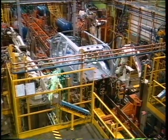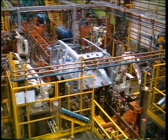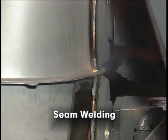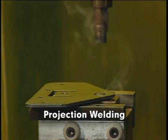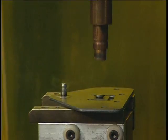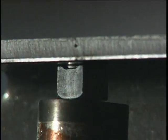Spot welding, with the electrodes maneuvered by articulated arm robots, is commonly used to join sheet components of automobiles. In seam welding, coordinated pulses of electric current from rotating wheel electrodes produce a series of overlapping spot welds, resulting in a leak-tight welded joint. In projection welding, the welds are localized at predetermined points by projections, embossments, or intersections. Several points may be welded simultaneously,